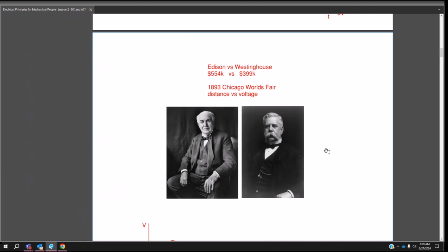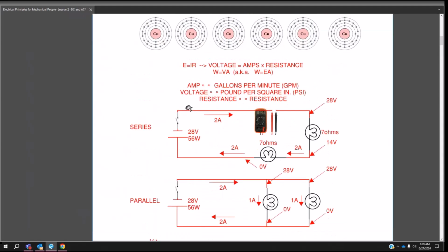So technically speaking, yes, copper and aluminum have inherent resistances. When we were talking up here, I said assume there is no resistance. Well, technically there is, but on short circuits, it's negligible. Completely negligible. Exactly. When you're getting into larger buildings, then you've got to look at it. Like high rises, where you've got to go up 30, 40, 50 stories, that's 300, 450, 500 feet, somewhere around there. Once you get to 150, 200 feet, that's when you start to worry about it, whereas that's analogous to 300 feet on a water hose. You're going to start losing pressure at that distance.